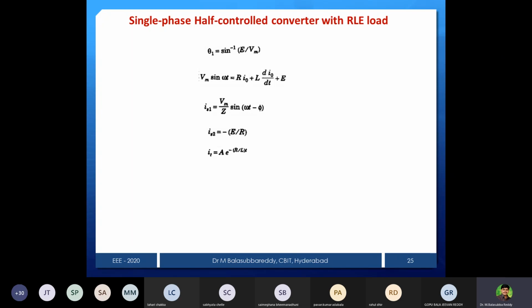That is the same derivation that I told you now. If we start with the half wave rectifier with R load, the derivations, theory and waveform need only a slight one step modification, not more than that. For R and RL load, you get the negative portion. For RL and RLE load, during the zero instant you will get the battery voltage. Remember that small difference, it is easy.